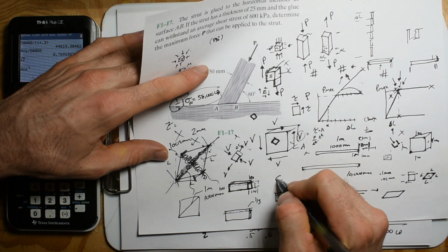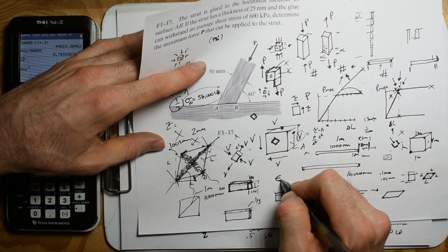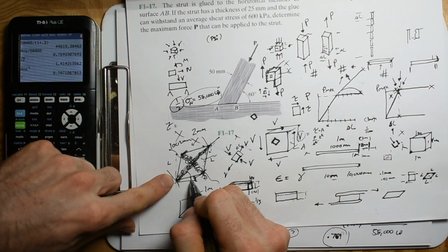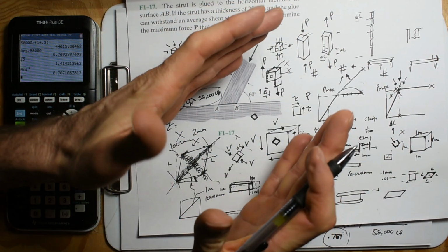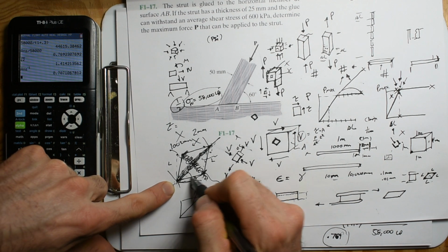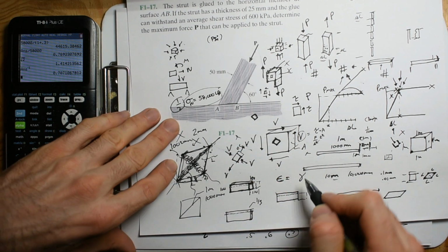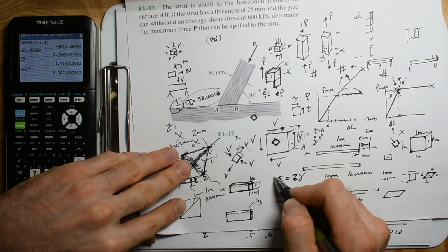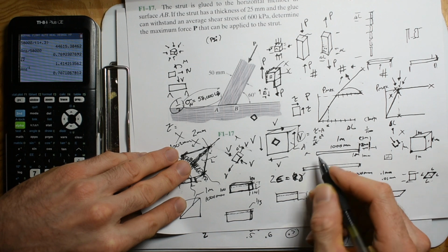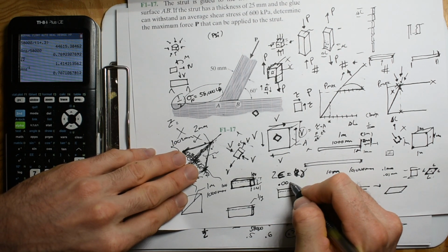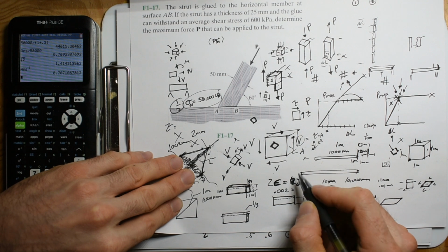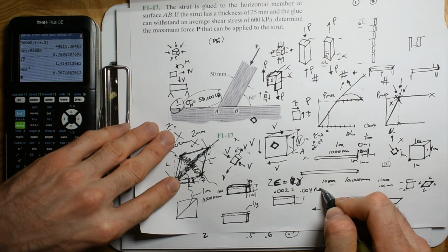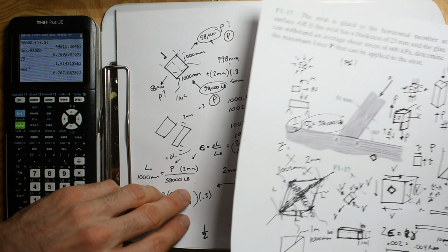If you're trying to relate the normal axial strains to shear, the angle of shear deformation causing something to turn into a diamond shape, then the relationship is just 2 times the normal strain is that angle. So for metal, if it's 0.002, then the angle is going to be 0.004 radians.